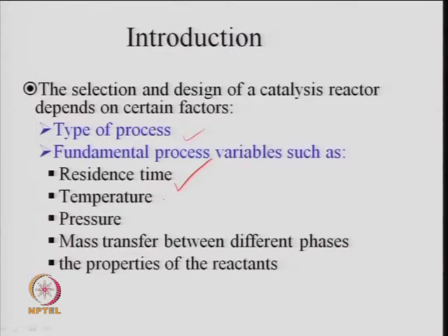Then of course, the temperature and pressure, because these are the kinetic requirements, and depending upon the reaction conditions we need to identify a definite temperature and pressure, and accordingly the reactor selection or its design becomes important. Then, during catalytic reactions we cannot eliminate the mass transfer between the different phases, and the properties of the reactant are also equally important.